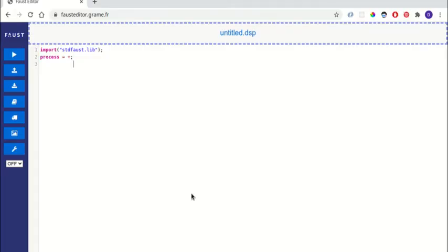4 steps to implement an audio prototype, almost without touching the C++ code, dealing only with the Faust script and testing it on a computer before running it on board. Let's start importing a Faust script on the Faust web editor.